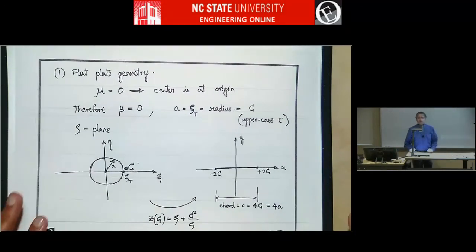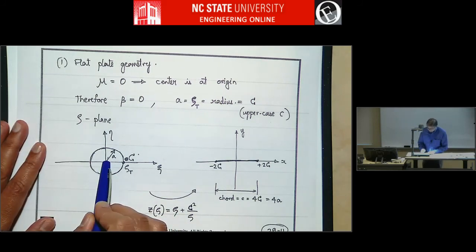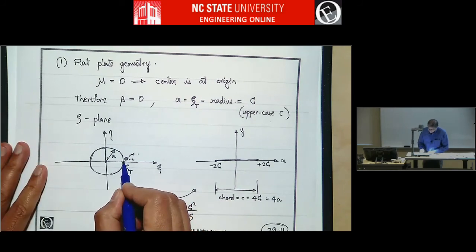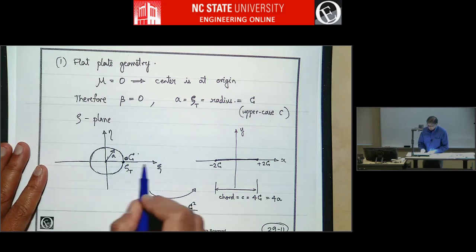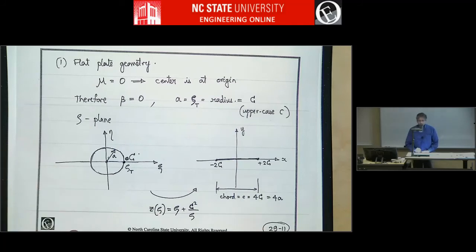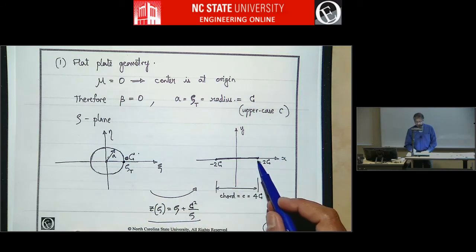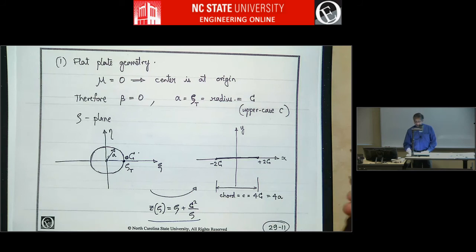First, the simplest airfoil we get is by putting the circle at the origin. So here we put the circle at the origin, so the radius is a, and this point, the zeta of t, is just where the circle intersects the horizontal axis. If you use the Joukowski transformation, which is this, and transform this, you will get a flat plate in the airfoil plane.